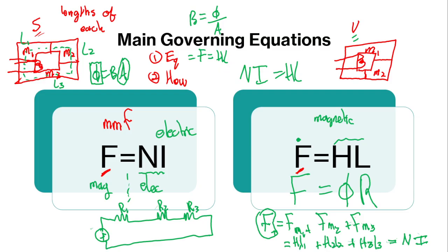If the area changes, would B change? That is basically the next question I'm going to ask. If the flux was the same, obviously you have different reluctances. But we know the flux will be the same, so you basically have to factorize the flux and calculate the reluctances. But now, if you have different cross-sectional areas, you will have to do what was done here.